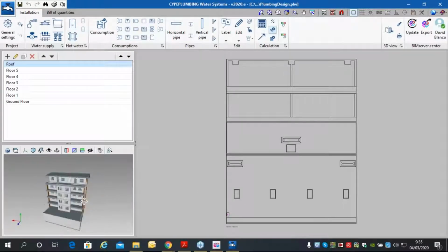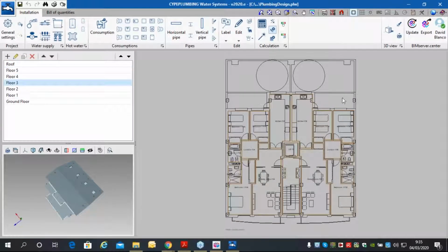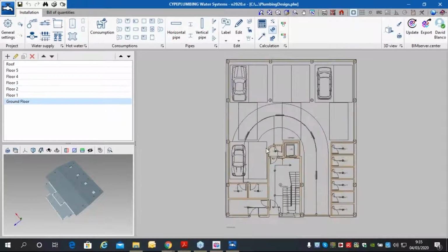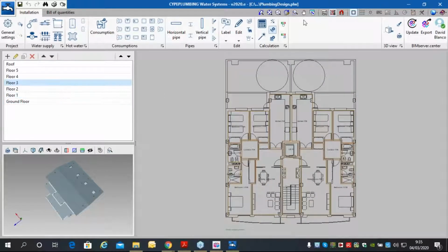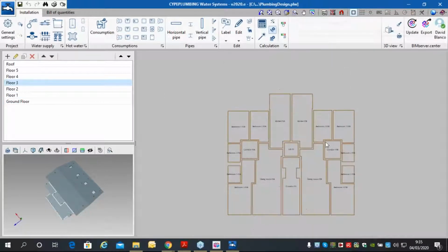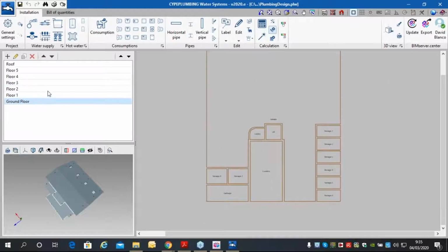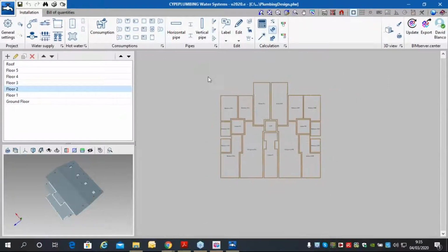So this is the workspace. I'm sure that rings a bell according to the previous open BIM systems you have seen in the previous weeks. So here is the 3D view of our IFC architectural modeling. And here we have the different floors with the templates on the right and the different rooms. We can activate or deactivate them with the shortcut F4 on the keyboard, or even with these icons you can activate or deactivate the different templates. So this is our design. So let's start designing quickly because we don't have so much time.